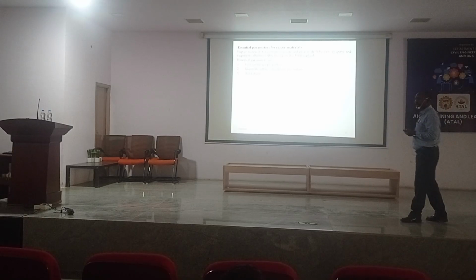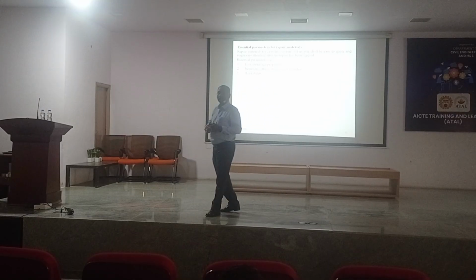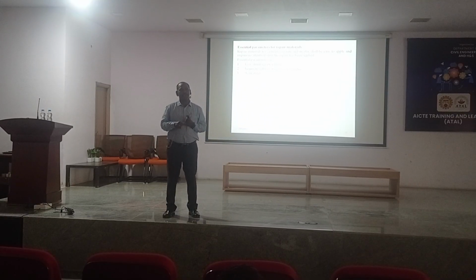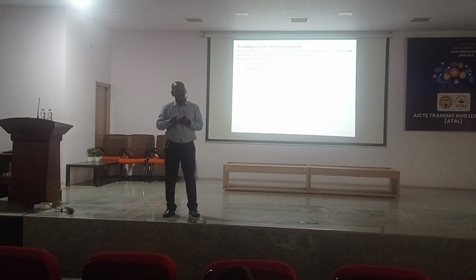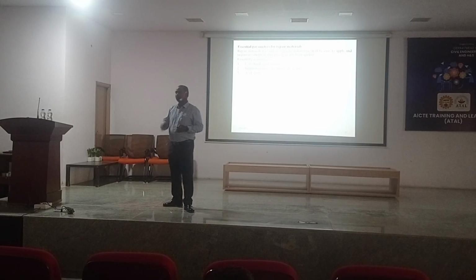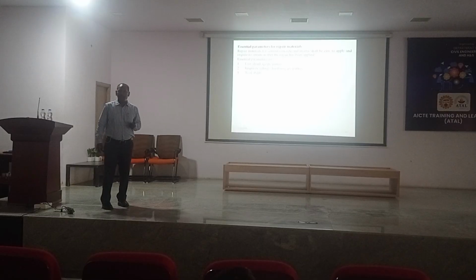And the third one is workability. Based on this workability, we choose self-compacting mortar as a repair material. Okay, what is the definition of workability? Everyone uses that as a civil engineer. Okay, what is workability? In a simple way we can say it is ease of working. Easy to work in all aspects: while mixing, while transporting, while placing. In all these aspects, the material should be easy to work with, handled with easiness. Therefore, the repair material should have good workability.